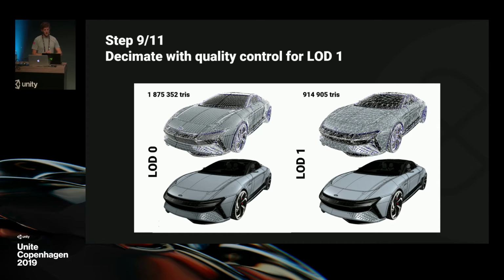For LOD number 1, we will use the mesh decimation function. And decimation in PiXYZ can be driven by either a polygon target or by quality control criteria. And these criteria can preserve the original shape, UVs, and normals, which can be very important for CAD models. We don't want things to look like a potato in the end. So for this LOD, we use the decimation with quality control. And we approximately cut the number of polygons by half here without losing shape precision from a very reasonable distance. Decimation is also a very, very important algorithm, and Cédric will tell you more about it.